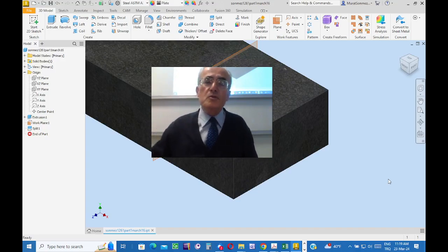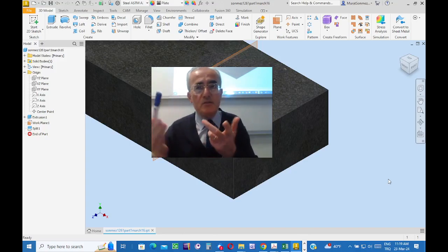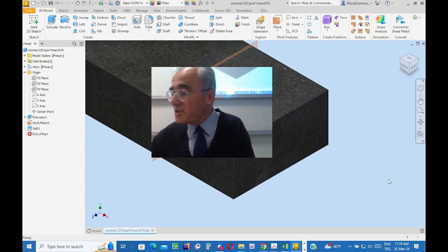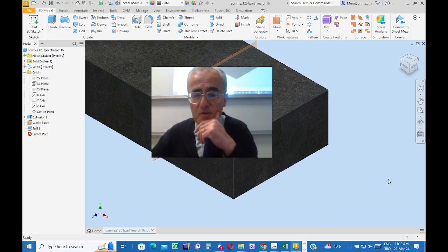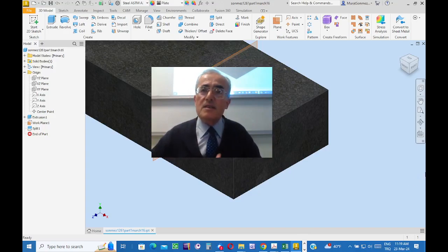But if you're going to use a cylindrical piece, rod, okay, cylindrical bar, the contact surface is going to be circular. Depending on which tool is going to be used for applying such a concentrated force, accordingly define the subregion. In this example, say that it is circular.